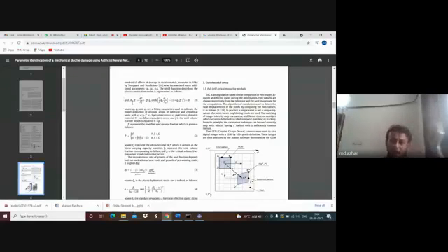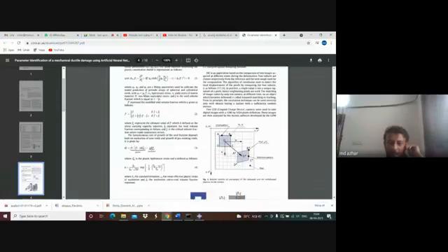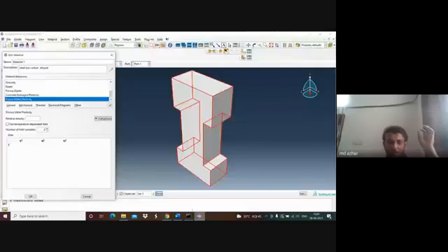So this is how they have formulated the mathematical model, and they have Q1, Q2, Q3 over there as constants, and then they have the F value. Then they have the Fn value, and then they have the Sn standard deviation value, and then they have epsilon P, the plastic strain, and the mean effective strain. So these are the values. Let us just go there and see. Suppose you are using that kind of ductile damage model, the GTN model. So this is what you will give.